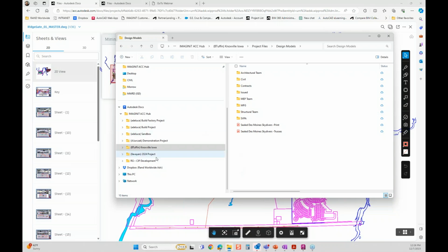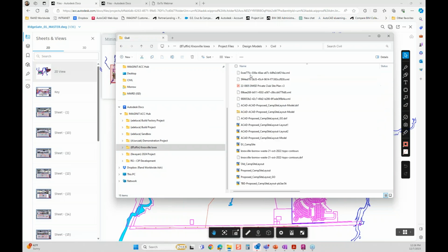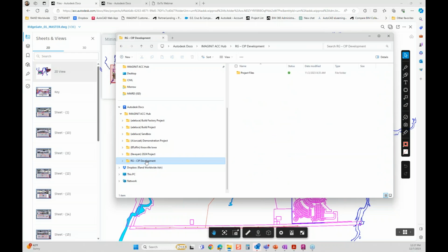So if I go to open up a file, whether this project template or this campsite, it's going to take me a little longer to open that file, depending on the speed of my internet connection. Once it's open, though, it's here locally, and it's going to keep that file here locally for 2 weeks by default. If I don't touch it in 2 weeks, it releases it back to this format where it's just in the cloud. That's a neat thing, because it helps automate control of your data on your local machine. That gives you the best of both worlds.